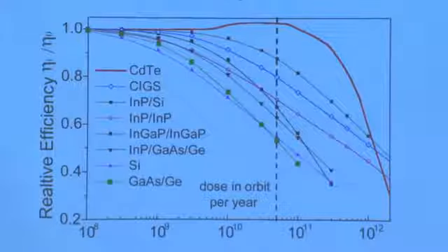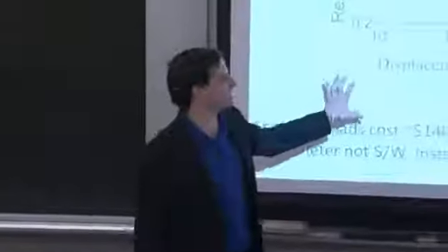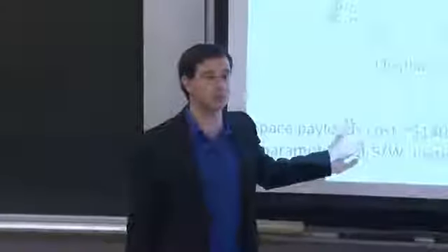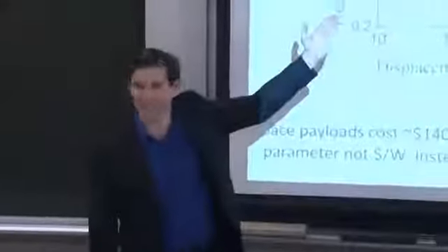So we have the radiation hardness to take into account if we're putting these solar panels out into outer space. This is one older study. I would definitely encourage you to look. There may be some newer studies. As the solar cell efficiency improves, they become more sensitive, right? Because you begin decreasing your efficiency with smaller variations in the minority carrier diffusion length. So those charts might look a little different as time goes by.